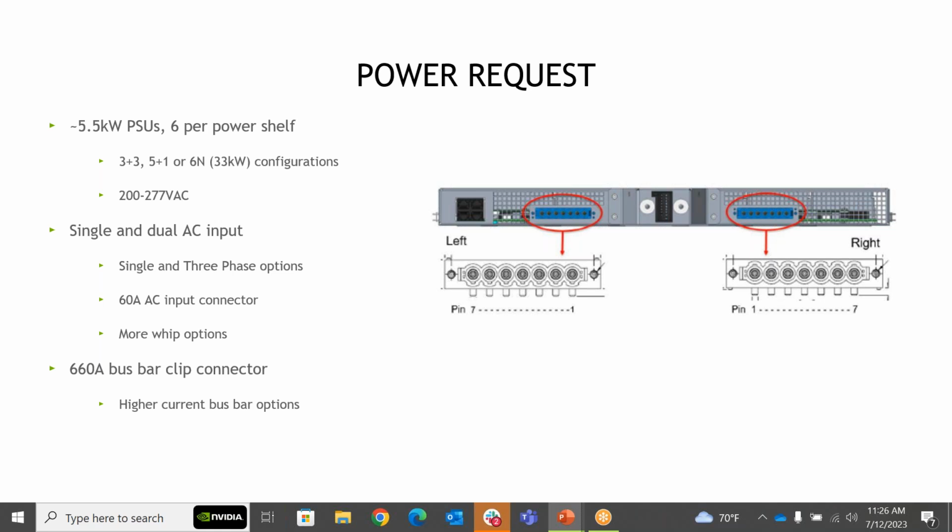Thank you, Manny, this is John Whitdell. I've got one quick question. Are you interested in or have you thought about the integrated ATS that some vendors have developed? I know you highlighted the N plus N, and I'm assuming that's from the input redundancy side, not necessarily a need for 2N for power supply redundancy. It has some trade-offs with capacity, but overall can significantly help with density by reducing the number of power supplies and power shelves.